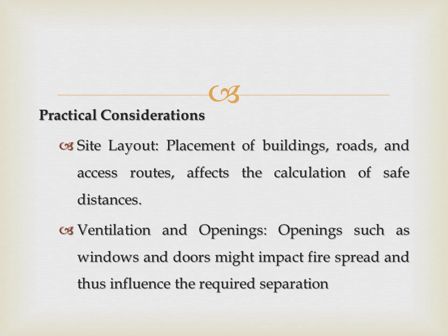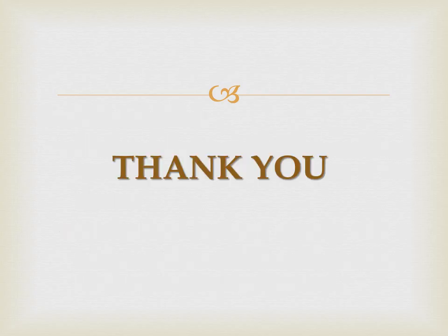Practical considerations. Site layout: placements of buildings, roads, and access routes affect the calculation of safe distances. Ventilation and openings: openings such as windows and doors might impact fire spread and thus influence the required separation.